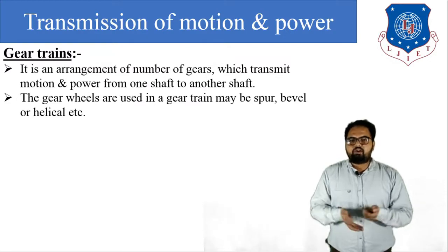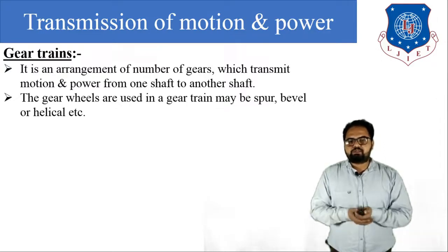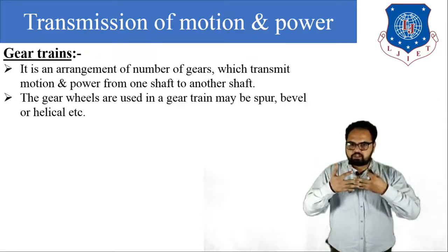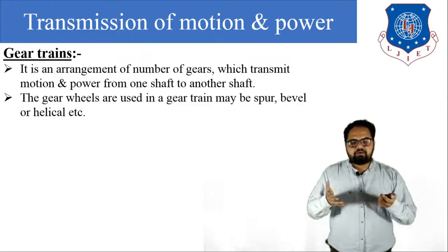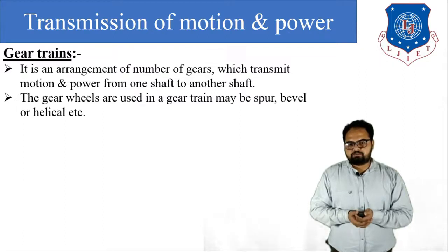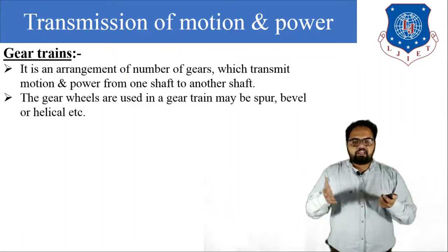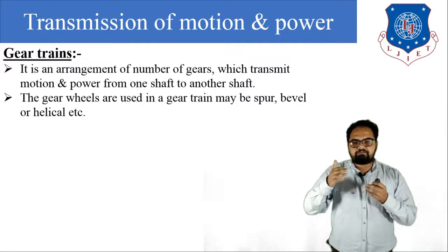helical gear. We have already discussed spur gear, bevel gear and helical gears. In spur gear, we know that the transmission of the power takes place when the teeth of the gears are in mesh with each other and both the teeth are parallel to the axis of the shaft. In bevel gear, when we require to transfer the power at 90 degrees, at that time bevel gears are used, and in helical gear, the teeth of the gear are similar to the spur but are at a particular